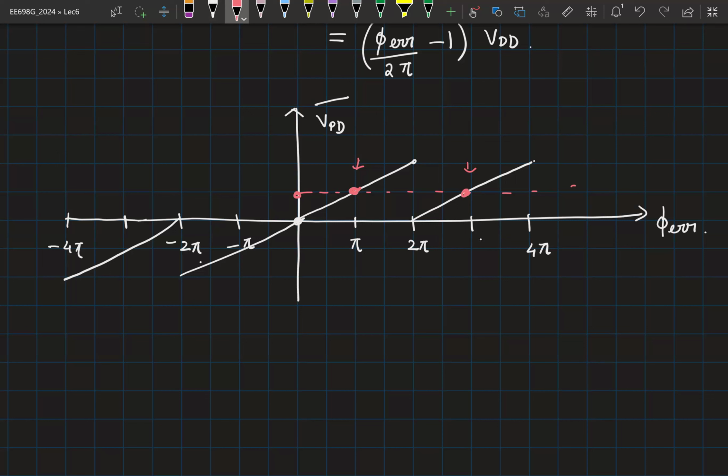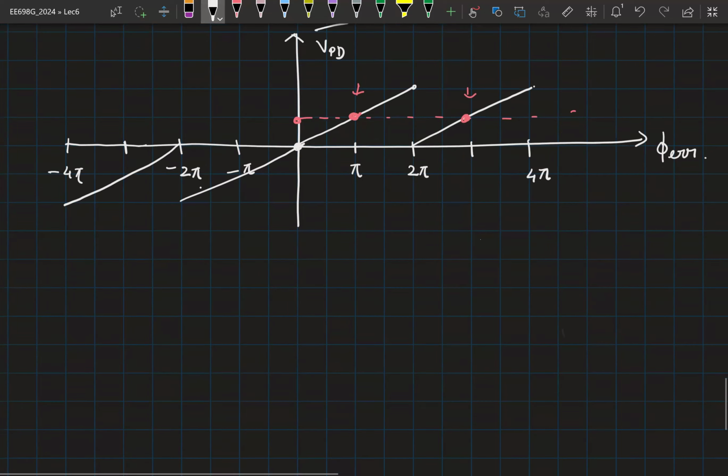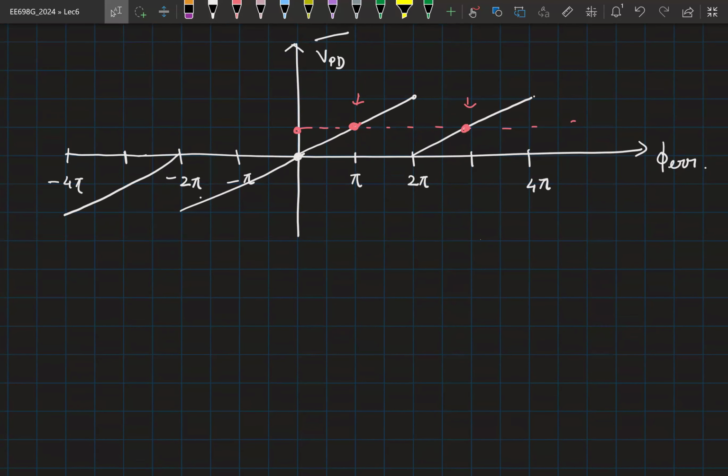Like it may happen that the delay of that VCDL may cross 2T naught. It can. But if you design your VCDL, the difference between the first edge and the second edge, it may happen it can cross 2T naught, then we will take the difference between the first, second edge and those things. Correct. That is correct. But now the thing is the VCDL design is under your control, right?